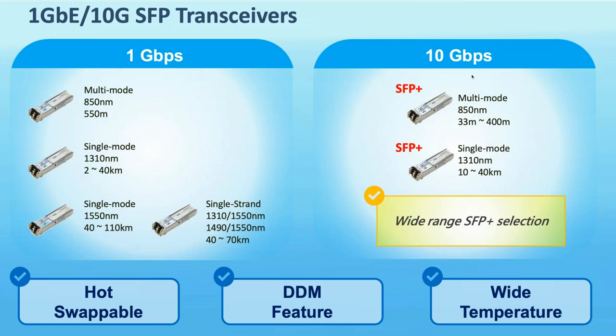Since they're SFPs, they're pretty straightforward. Everything's hot swappable. We have digital diagnostics within the SFP, so you can see things like your transmit strength, receive strength, operational temperature of the SFP as well. And talking of temperature, all these SFPs support wide temperature, and they're designed obviously not only to fit into the 10 gig switches I've been talking about now, but into any other switch manufactured by Advantech as well.